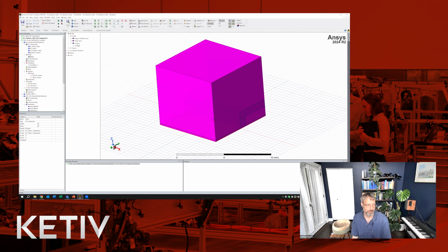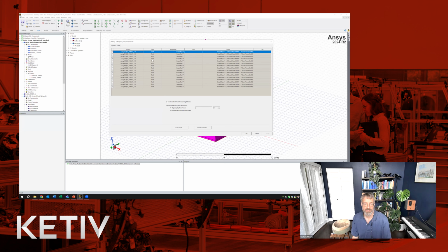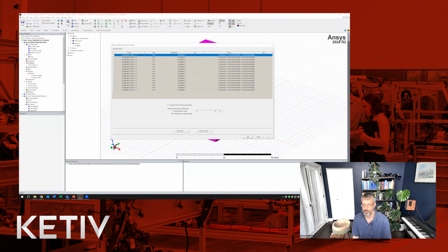And then once we have the array, each of those patches, which has its own port, gets pulled in here. In this case, we have a 4x4, so we have 16 different inputs here, and then we can add these equations to help with phase shift and scan magnitude as a variable that allows us to change the beam forming and how it's formed.